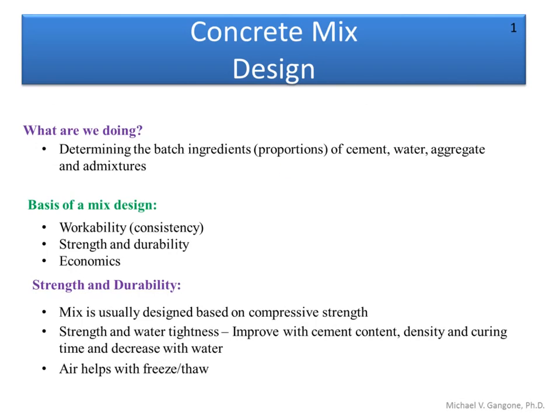Mix designs are based primarily on three things: workability and consistency, strength and durability, and of course economics. With any material that you deal with, no matter what it is, civil engineering or mechanical engineering, whether we're dealing with wood, timber, masonry, metal, concrete, strength and durability are key. The material must have appropriate strength to carry the loads that are going to be required of it.